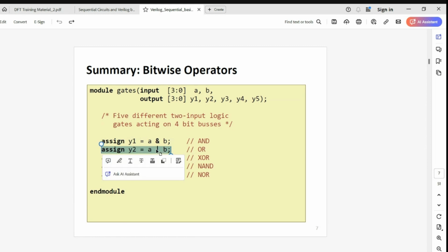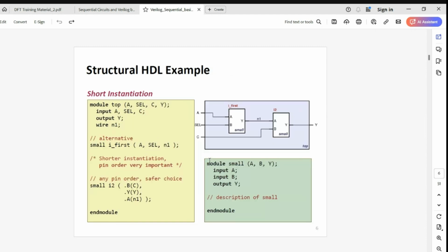When you write these and give them to the synthesis tool, because RTL has to be synthesized to gate level to start working for the physical design team, or for the DFT also if they are using a netlist flow. If you give it in this way, the tool will convert these symbols into the XOR behavior. The tool will find a suitable XOR gate from the libraries, as you saw in the previous image, and instantiate it here. So once it's synthesized, it will get converted like this.